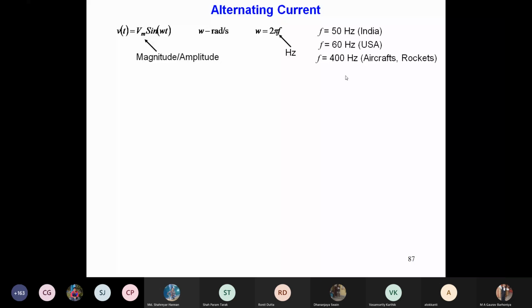It will fly over the North Pole. So for 15 hours, the power has to be there. It has to have sufficient energy. If it carries a bulky generator, it will act as payload, so the generator size has to be brought down. If you increase the frequency, the generator size comes down, the machine size comes down. That can be shown mathematically. I will show it, if time permits, when we discuss the motors, that if the frequency increases, the size of the machine comes down. It is the design.